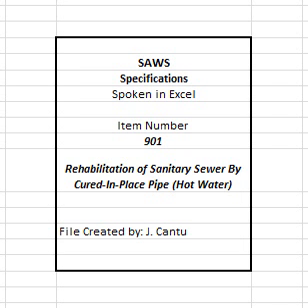B. Defects such as foreign inclusions, dry spots, pinholes, delamination, lifts, seam separation, lateral overcuts, and wrinkling beyond the specification allowances, determined by the engineer as affecting the integrity or strength of the CIPP, or as adversely affecting the hydraulic capacity of the pipe, shall be repaired or replaced at the contractor's expense. Method of repair shall be proposed by the contractor and submitted to the engineer for review and approval.